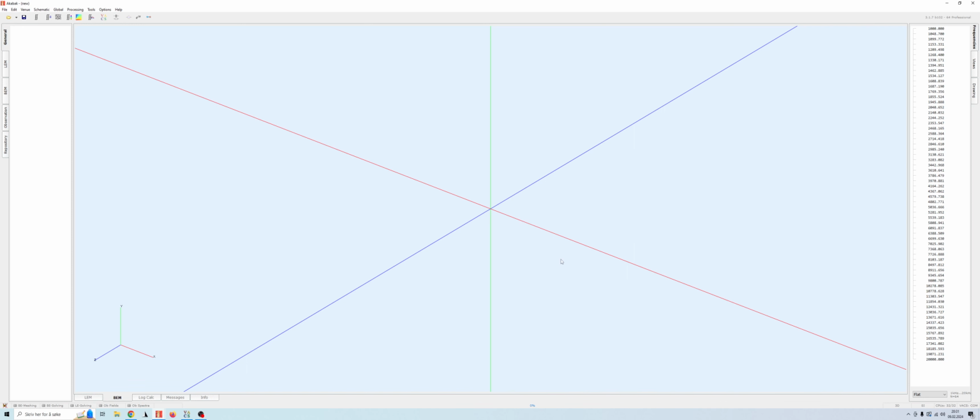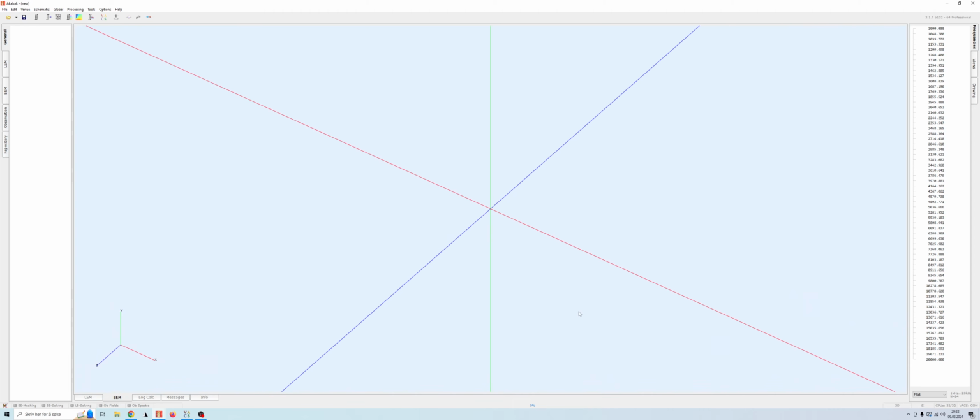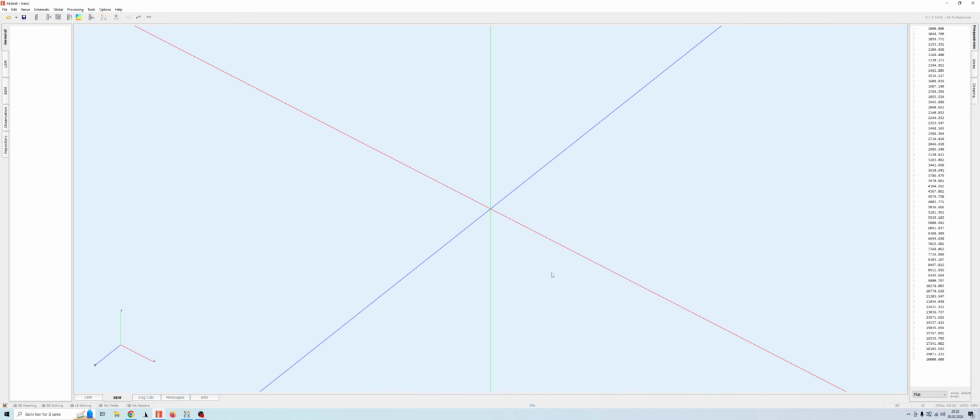This is especially true for larger rooms or rooms where you want to simulate to a relatively high frequency. To begin with, AKABAK accepts DXF files for the 2D mode, .dxf files. The biggest problem with this is that AKABAK doesn't seem to like a lot of DXF files. For example, if you try to import a DXF file which has an arc in it, the arc will be